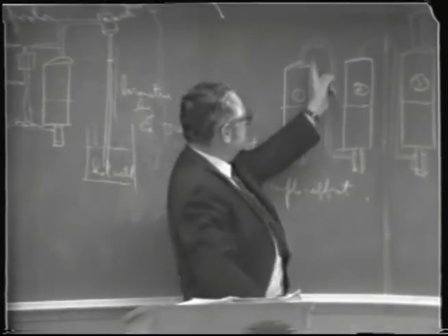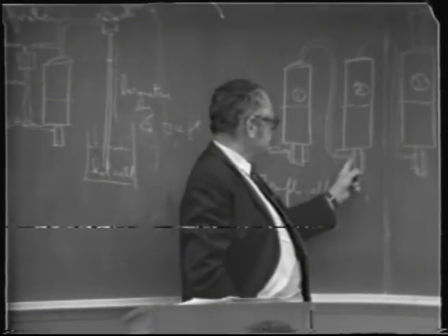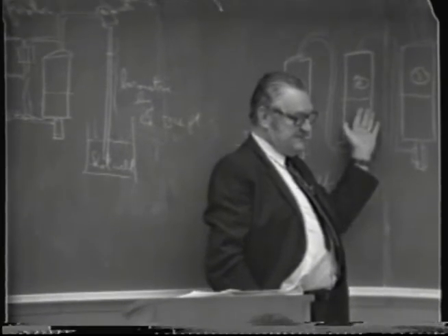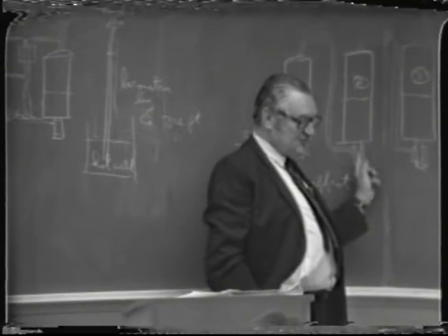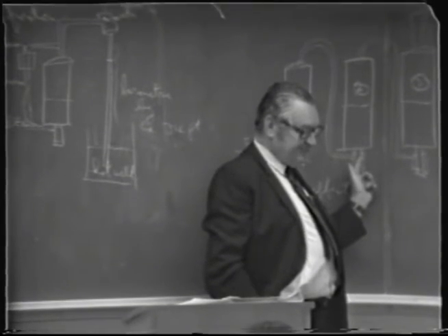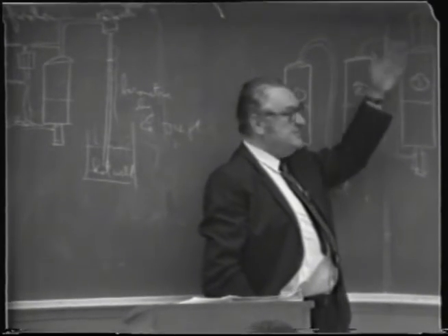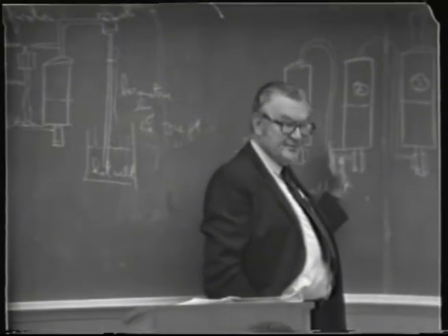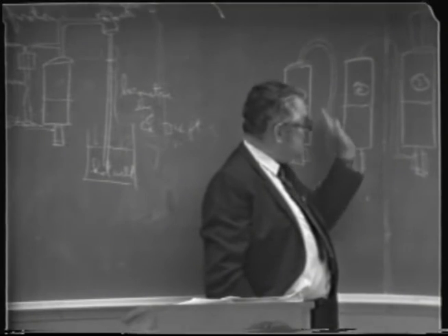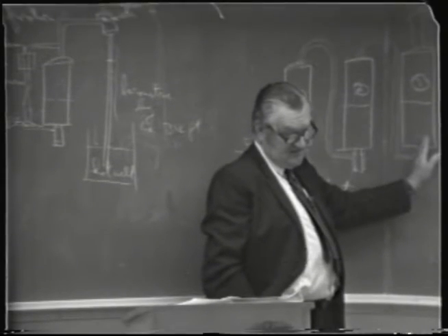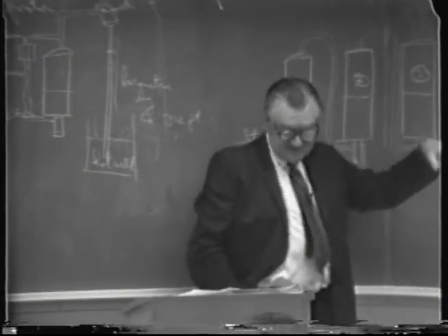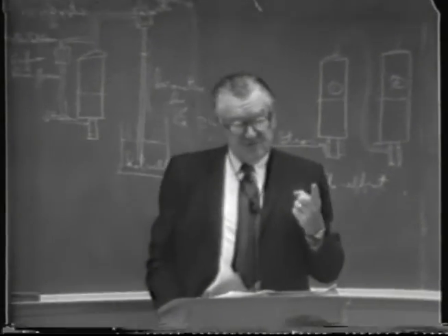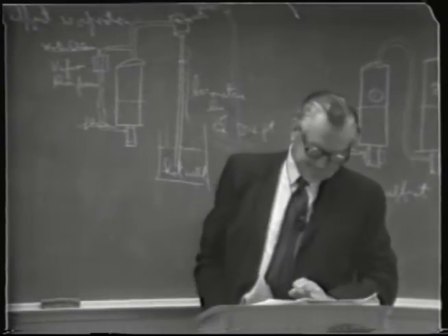Now, if you have a triple effect, and you can reuse this steam by operating this evaporator body at a lower pressure and therefore a lower boiling point, you'll get essentially another pound evaporated. And similarly in the third effect, you get another pound evaporated. So here you get an economy of only requiring 1 pound of steam for 3 pounds of vapor evaporated.